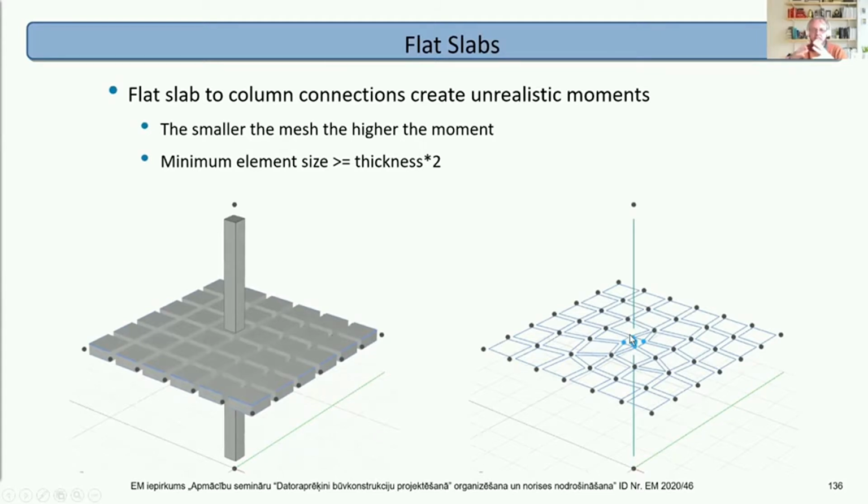So mathematically speaking, if we reduce these mesh elements down smaller and smaller, the bending moment will increase further and further. And there comes a point where we as engineers will go, no, it's not relevant anymore. The analogy has broken down, and we say no, just stop at this point. So yeah, this is 1 to 2D connections, and also wherever you get sharp changes in direction.